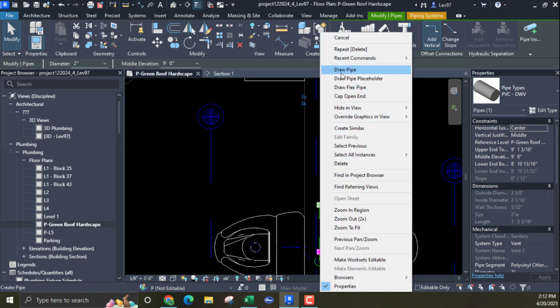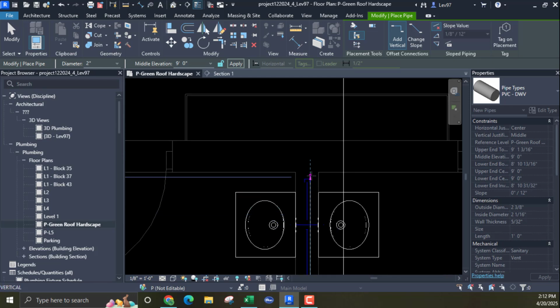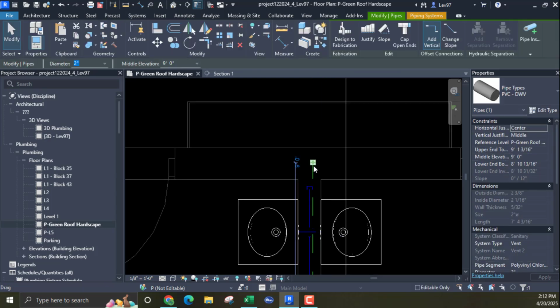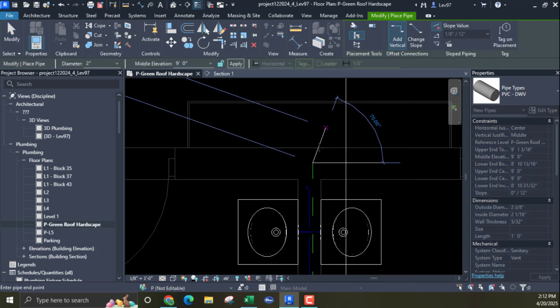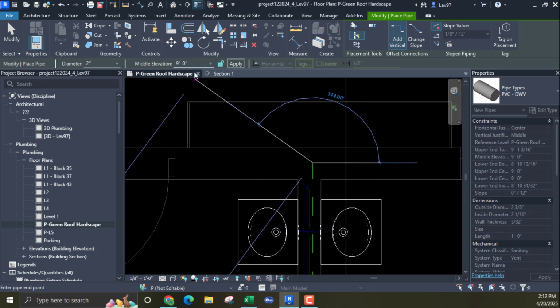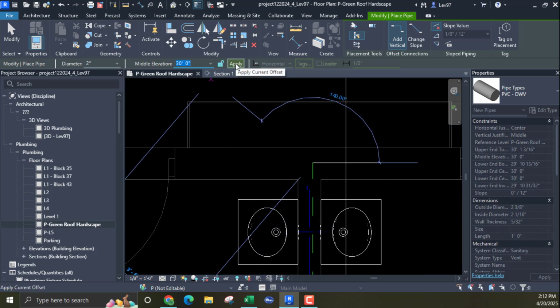So I'm in the wall space. In the wall space, and maybe here and go up. Let's just go up. But we have to see how we're going up and how we're penetrating. So I'm going to go here and choose 30 feet, which is probably good, and say apply.